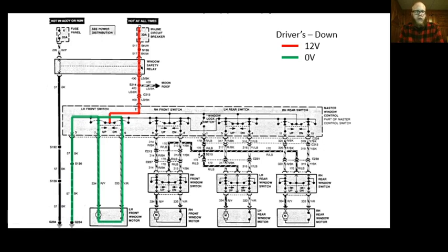The window motors are in the doors open and close, and it's not uncommon to stress the wire out and have eventually the insulating coating wear off, and then the wire will even break. And what this does is it makes it so that we won't open up this circuit breaker at the top unless we have the door in the position in which metal is touching, which might be open, and we're trying to move the window up or down depending on which one of the two wires have gone bad, right?